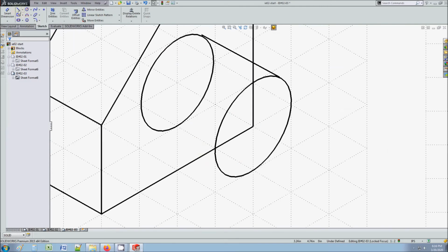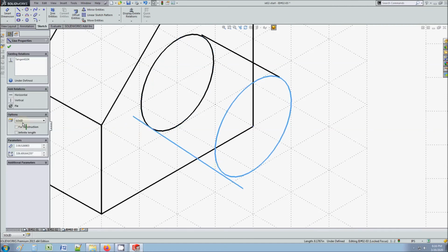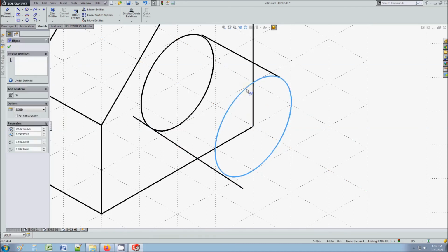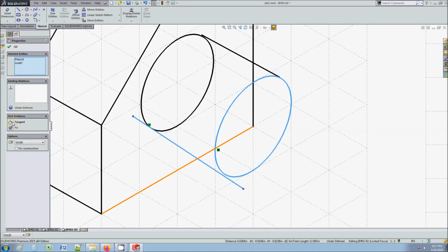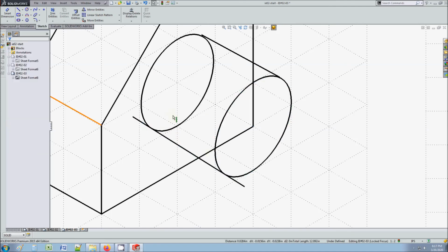If you don't want to eyeball it, you can use relations for that. Just add tangent here, add a tangent there. So that's a much cleaner way to connect. But you see something that jumps around because the way I restrained it is not correct. So I gotta fix it. Gotta anchor it so it does not jump when I put my tangent. Okay, so now the back is jumping around. Okay, so it's not perfect. Let's see if we can make it. Okay, there you go.